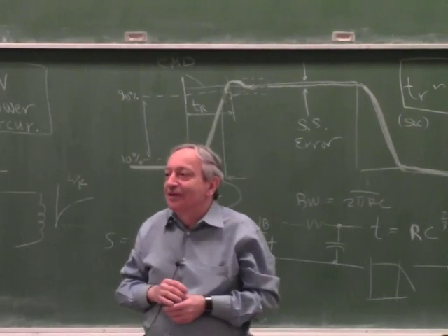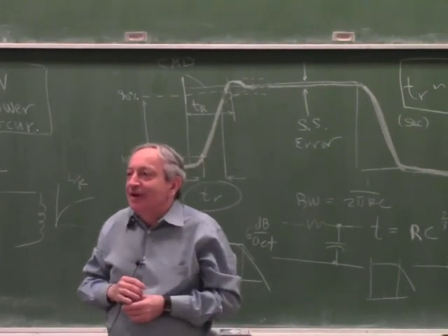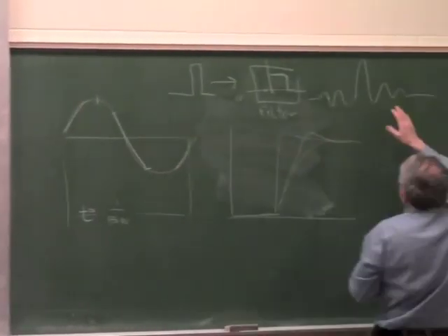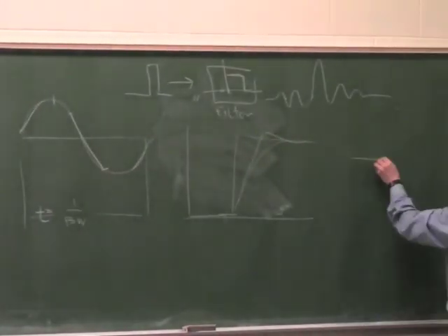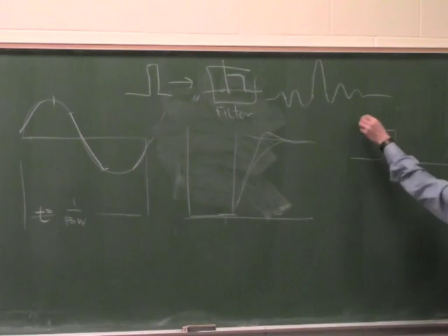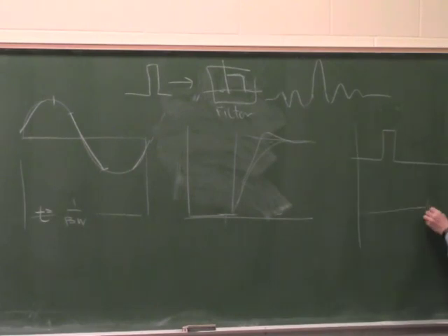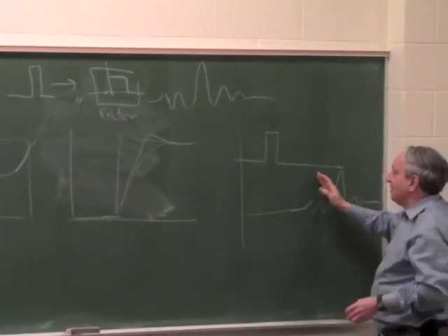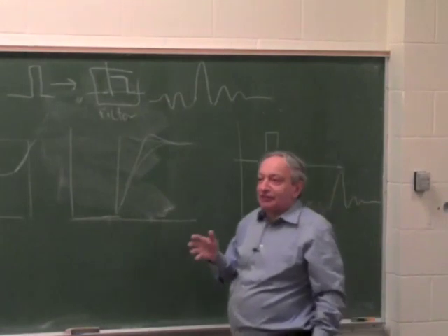Yes? The whole thing's delayed? If correct, very good. Because actually, if you line them up in time, the input pulse looks like this, and the output pulse starts much later, because the filter has a delay. So, of course, it doesn't see the future. It starts ringing much after this pulse. And the more stages you have in the filter, the more delay you have. But the more delay you have, the worse it is for a servo system.